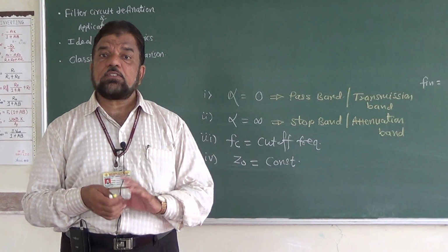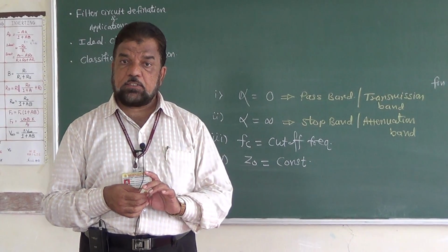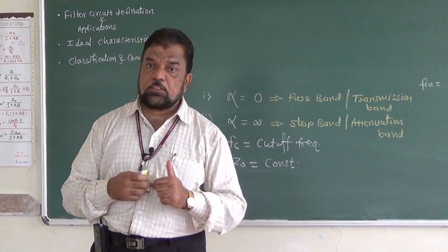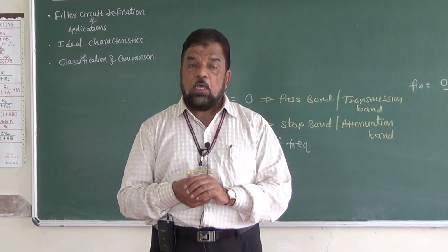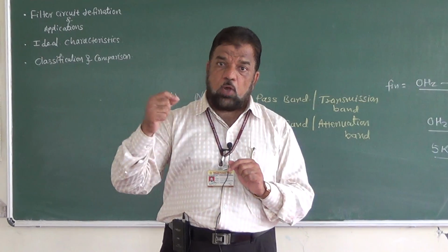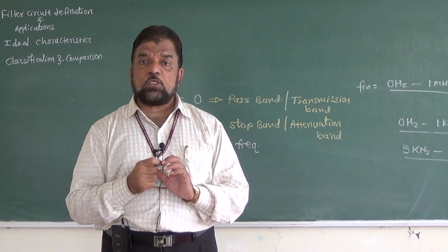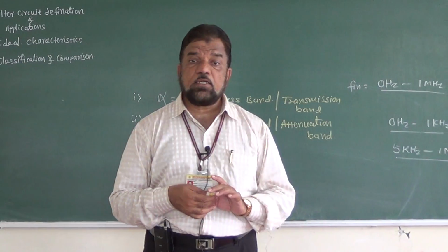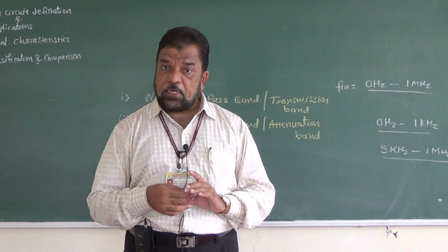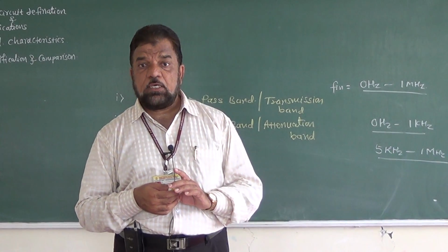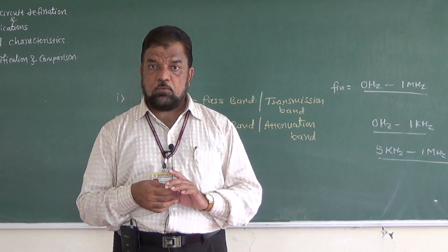And these ideal filters are constructed from pure reactances. That means I have to use an inductor and a capacitor, and the assumption is that the inductor, that coil, does not have any series resistance. Similarly, whatever capacitor I am using does not have any dielectric loss resistance in the ideal scenario. While designing the circuits practically, we have to select L and C such that their resistances are as small as possible.